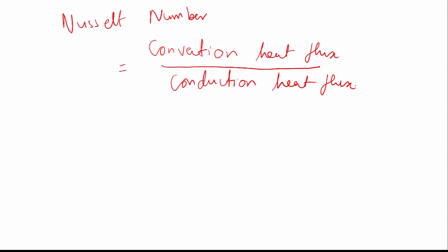Once it reaches unity, the heat transfer changes from convection heat transfer to conduction heat transfer. Then the convection formulas are not applicable for that situation; you can use the formulas for conduction heat transfer alone. Therefore the Nusselt number is always greater than unity for convection heat transfer problems. This is the main important parameter and an important concept for the convection heat transfer coefficient.